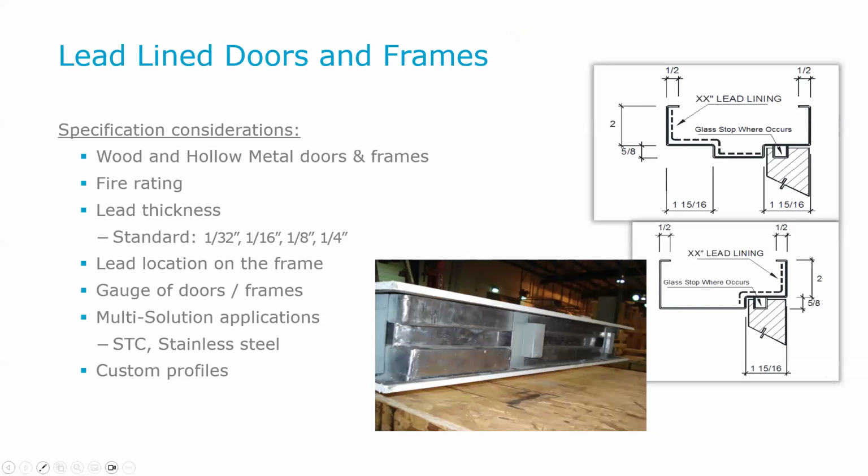But really, when you get over 1/4 inch thick lead, that's when you really want to make sure that the product can be manufactured. I think back on the instance of the 1 inch thick lead, which was a cancer treatment facility where they housed all of their treatments. That whole area, they wanted to be 1 inch thick lead: doors, frames, walls, everything. So again, you want to be aware of the lead thickness that is required on these types of projects, depending on where that door and frame is being used.